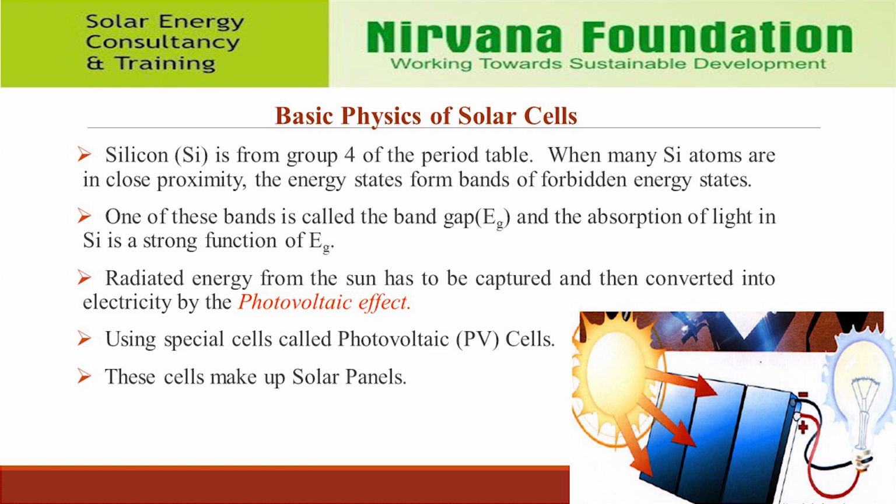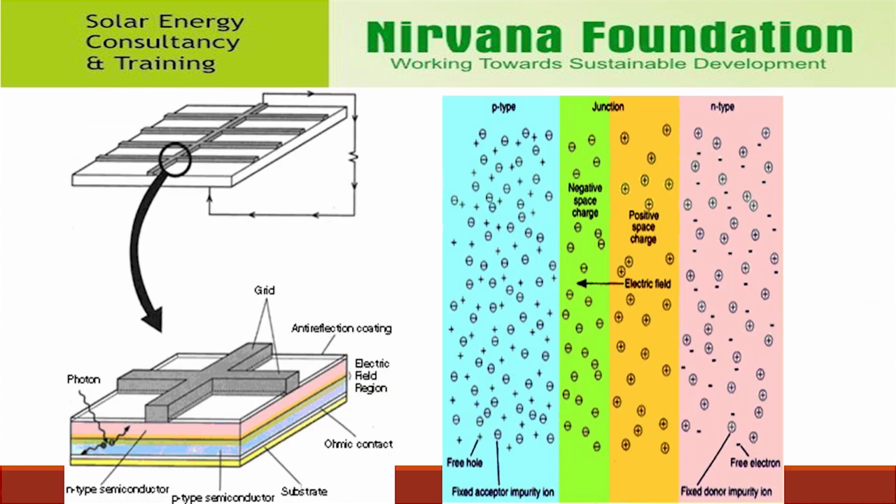The N-type silicon is made by including atoms that have one more electron in their outer level than does silicon, such as phosphorus. Phosphorus has 5 electrons in its outer energy level, not 4. It bonds with its silicon neighbor atoms, but 1 electron is not involved in bonding. Instead, it is free to move inside the silicon structure.